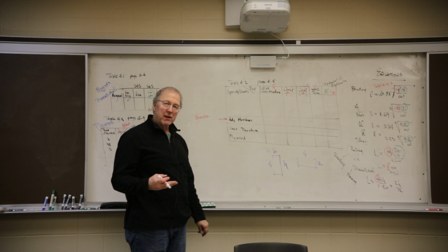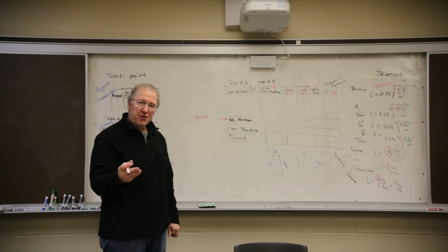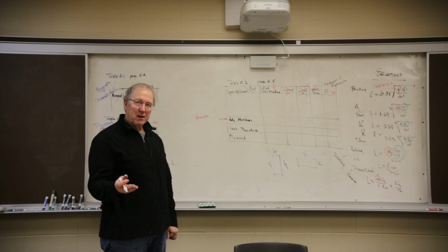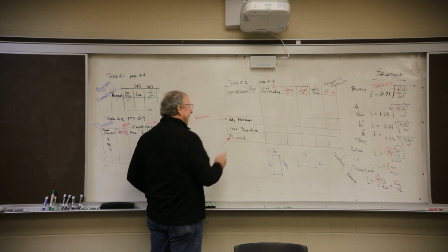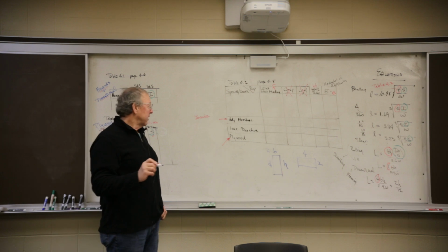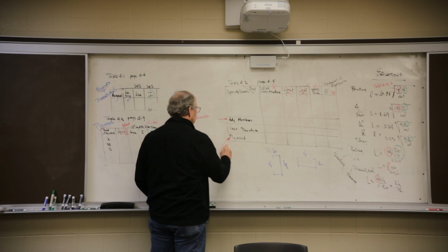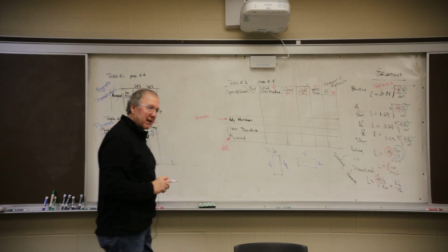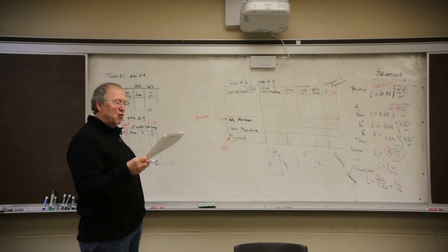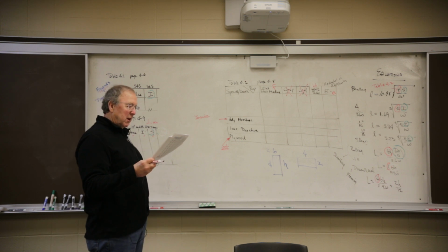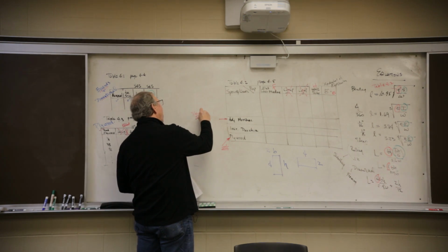We only have 2 types of sheathing in this particular part of the course. One part is boards, the other part is plywood. Plywood is taken care of down here. And plywood already has moisture considerations taken care of. So this is already wet. You don't have to put any factor on it. It's done. If you read it closely, you can see plywood sheathing used wet. Okay? So the only time you're going to use this is we've got sheathing and it's boards.